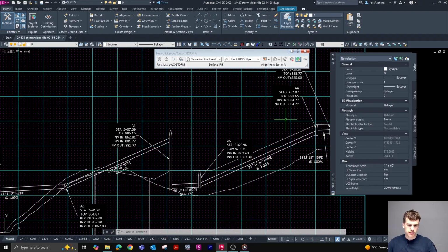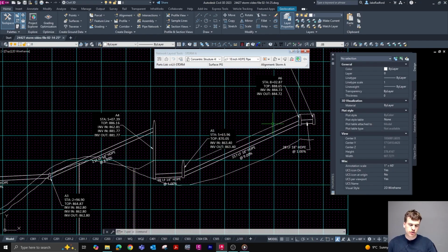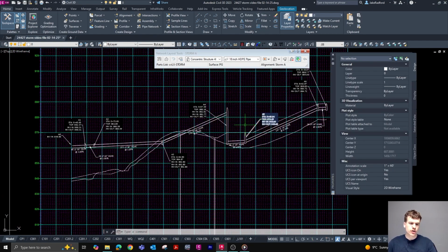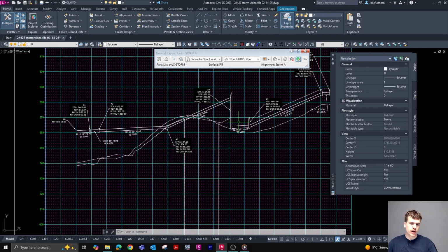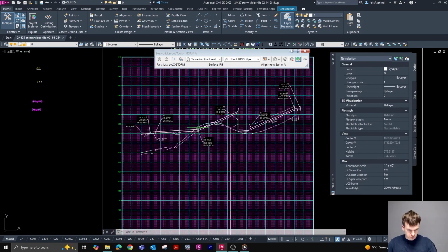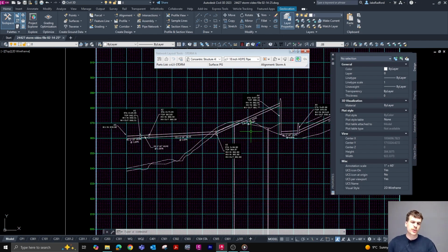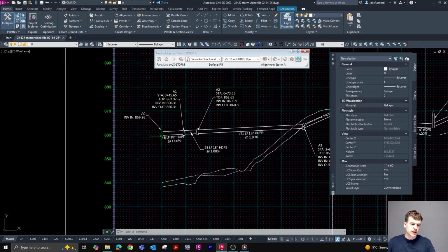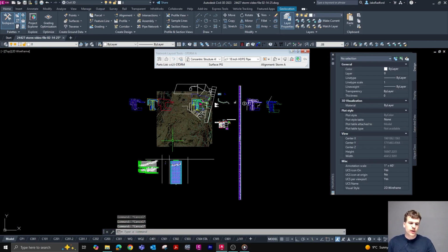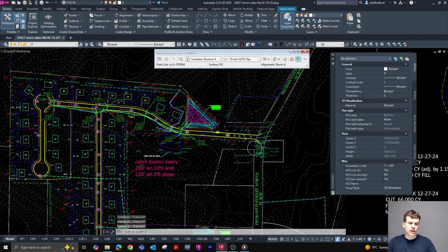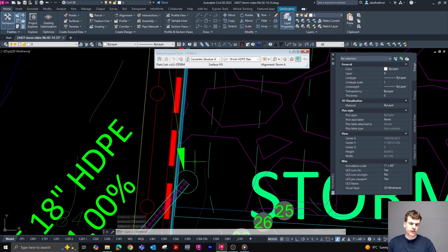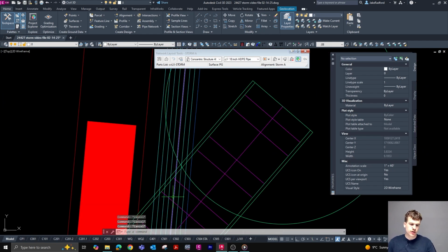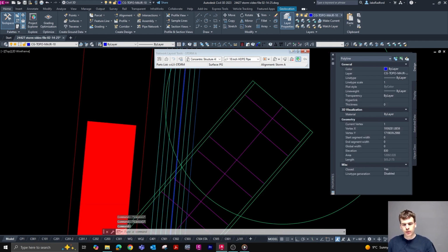So we've got pipes floating out of the ground. We've got a super steep slope here, so we're probably going to be more stressed on cover in this center area as well as these areas with steeper slopes. We can do the exact same thing from downstream to upstream, which is probably what you're going to do, right? So what's an appropriate elevation for our pipe to outfall into our pond, right? So we've got all these elevations here in the pond. The pipe might be halfway up the wall at 830.